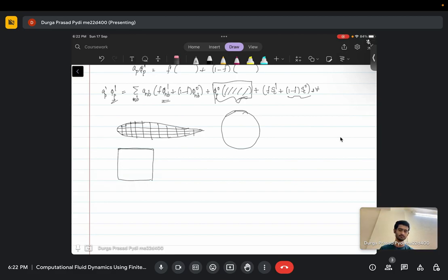Okay, so even if we use unstructured mesh, we'll get almost the same results. Yeah. But when you make it structured, you will have different nodes, and when you make it unstructured, you will have different nodes. So it is quite complicated, right? How do you say both are the same? You have different nodes here and here. So you need to do proper interpolation, get the values and compare, to define your metric. Yeah, got it.